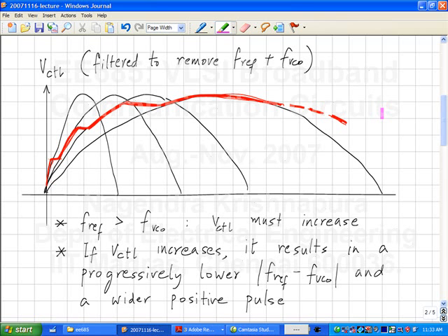In this case, there is no divider, so it's just FRF minus FVCO. With a multiplier, when you feed two frequencies, you will only get two other frequencies out, right? So you get FRF plus FVCO and FRF minus FVCO, assuming the sum frequency is completely filtered out. So essentially what happens is it may lock immediately, or at least it looks like it is trying to give you a larger positive DC average value, right? The positive component is increasing. So here I assumed that the control voltage started off increasing.